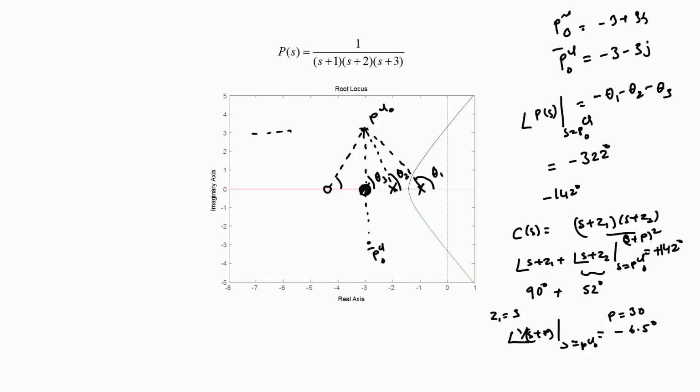So, the 2 poles put together therefore contribute minus 6.5 each, so the angle of 1 by S plus P the whole square at the point S is equal to PCL naught will be equal to minus 13 degrees. So, what we now have to do is to fine tune the positions of Z1 and Z2 so that they now compensate for this extra phase deficit that has come about because of the 2 poles that we have added to the controller in the interest of causality.